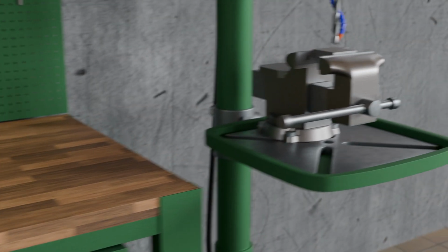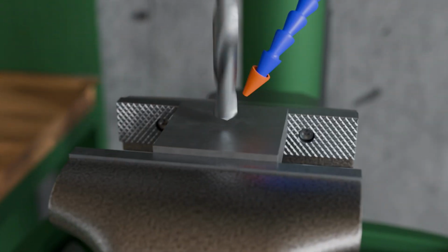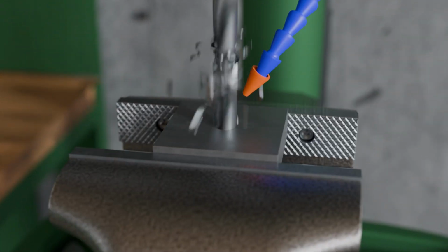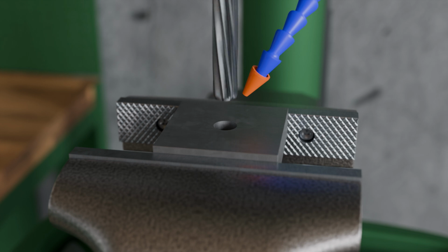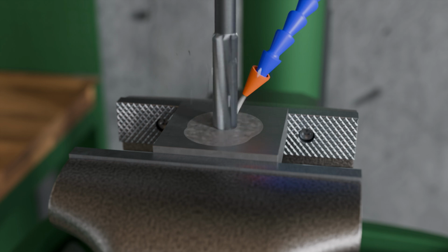Drilling with a twist drill is usually not sufficient here to meet the required dimensional tolerance of 21 micrometers. This generally applies to fundamental tolerance grades up to 10, which cannot be achieved with conventional twist drills. Therefore, the hole is initially pre-drilled with a twist drill so that the hole is approximately 0.2 mm smaller than the nominal size. Then the hole is reamed to the desired size with a special tool called a reamer. In the linked video you will find more information about drilling and reaming.